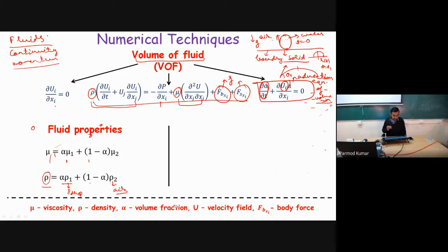Okay, so till this point, we have seen what the governing equations are which we have to solve. Now, we have to initialize. So while the drop will be moving, its contact line will be moving something like this. So when the contact line is moving, we have to specify some value of contact angle as a boundary condition.